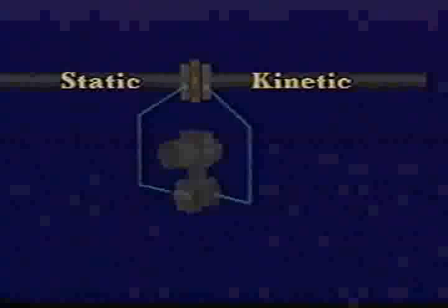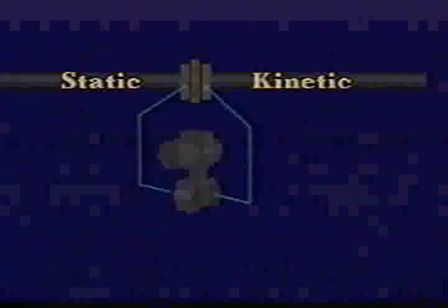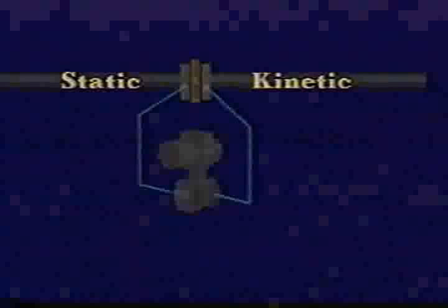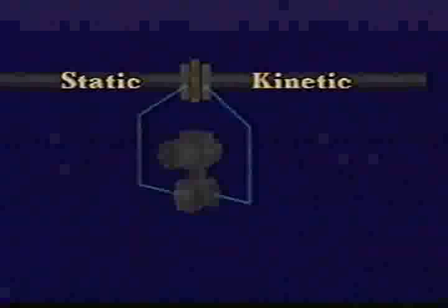The orifice plate is placed in the pipe in which the liquid travels. As the fluid passes through an orifice plate, static pressure changes to kinetic energy in the form of velocity. The differential pressure transmitter measures the pressure drop created by this change. The amount of pressure drop produced depends on the volumetric flow rate. The differential pressure transmitter measures pressure at two different points, upstream and downstream. The differential pressure reading is the pressure drop across the restriction. Differential pressure, then, is the difference between the higher pressure or upstream reading and the lower pressure or downstream reading.